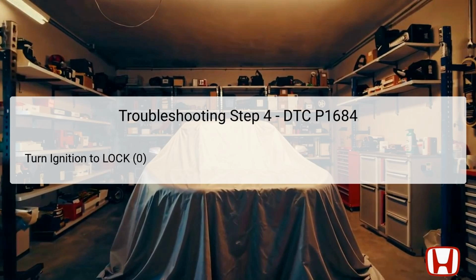Once the engine has idled appropriately after conducting the RPM test, the next step is to turn the ignition switch to the lock 0 position. This action will completely shut down the vehicle's electrical systems, ensuring no interference during the next steps of testing. Waiting for about 10 seconds is crucial here, as it allows any residual systems to reset.